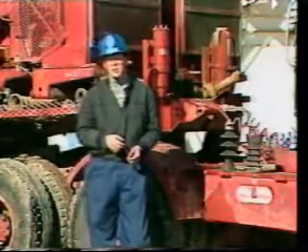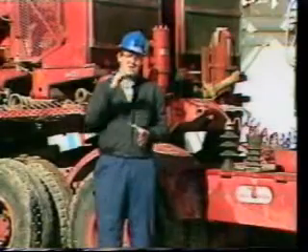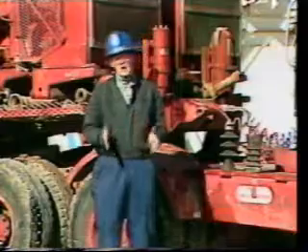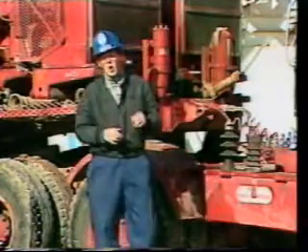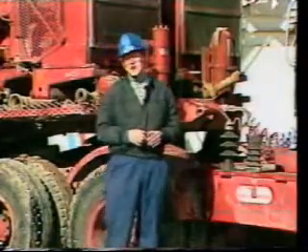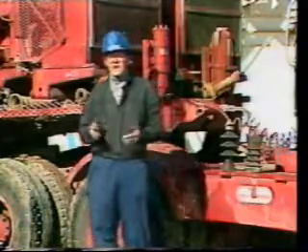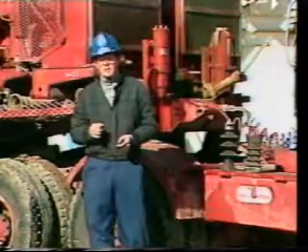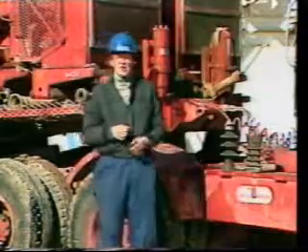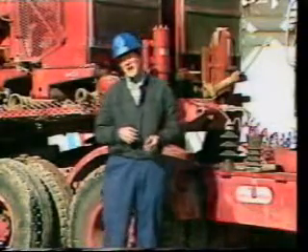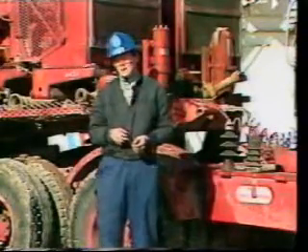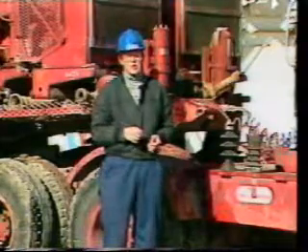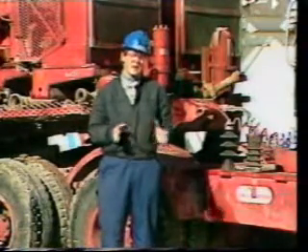The cement is pumped through a cementing head attached to the casing at the surface, on down the inside of the casing and up the annulus between the casing and the hole. The displaced drilling mud can be seen flowing out at the surface. Plugs, such as these, are dropped into the casing both before and after the cement slurry is pumped to isolate it from the drilling fluid ahead and the displacing fluid behind.